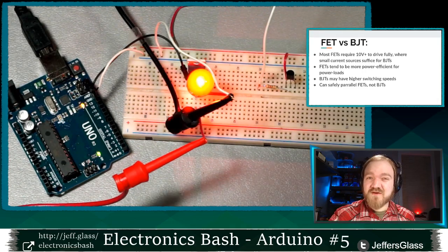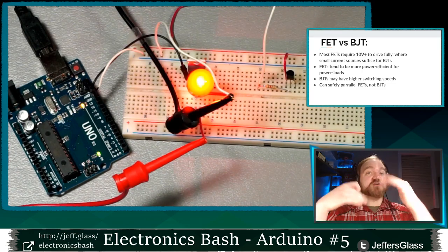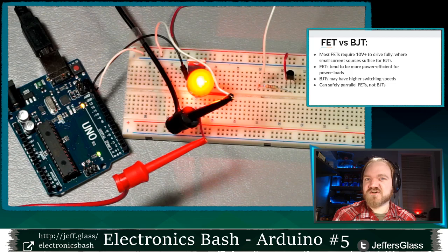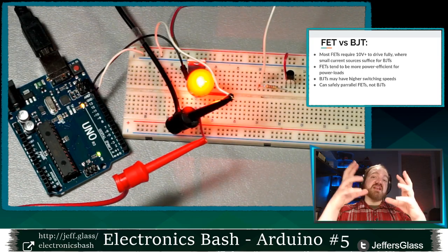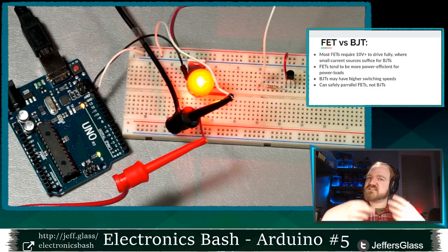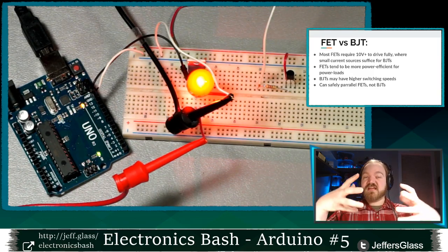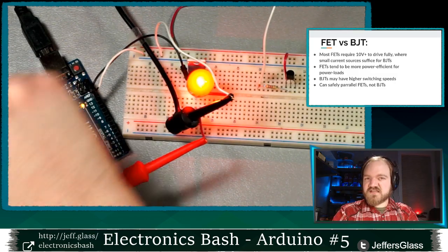And most of the time, it will work just fine. They won't necessarily evenly share the load, right, because those threshold voltages might be different. But in terms of how they're going to behave when they start heating up, they will tend to, when they're absorbing that power that you're putting through them, as an individual FET heats up, it will take less of the current through itself and sort of spread the load to the other FETs, which then themselves will heat up more and pass the current back to the first one. There's kind of this self-equalizing process that happens.